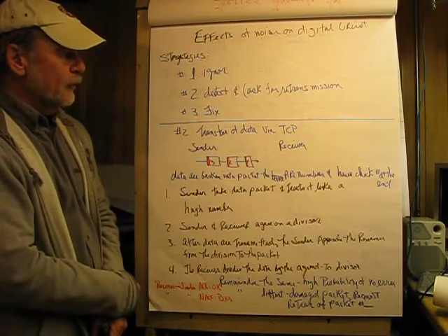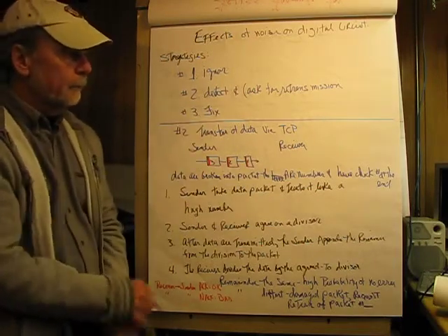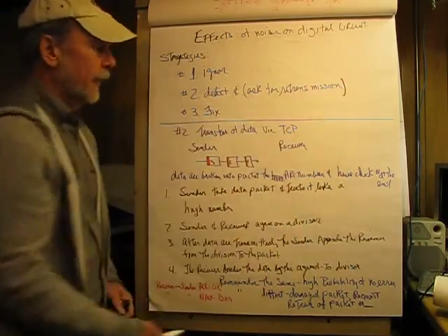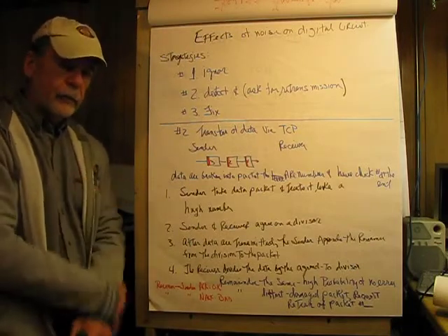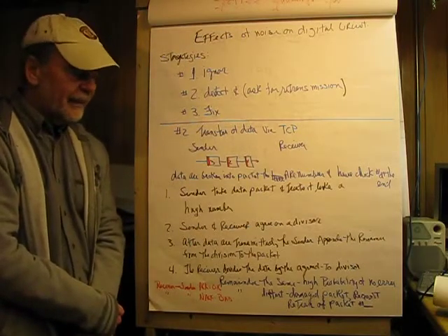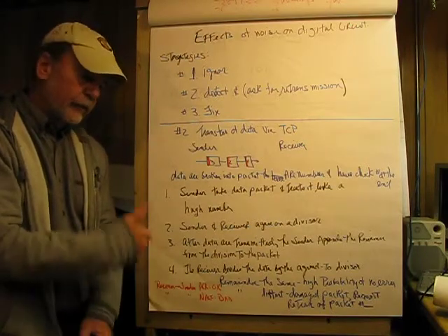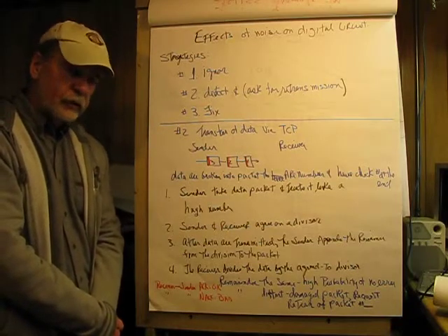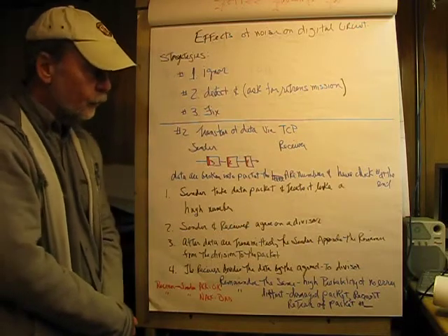So we have the option with detecting errors sometimes to retransmit the packet. So if you download a file over the internet, you can certainly do that, but if you're receiving a digital broadcast on your television set, it's kind of hard to say stop what you're doing and resend the packet, because the last picture I received had a noise blotch in the corner. So television transmission has to use a different way of mitigating errors.